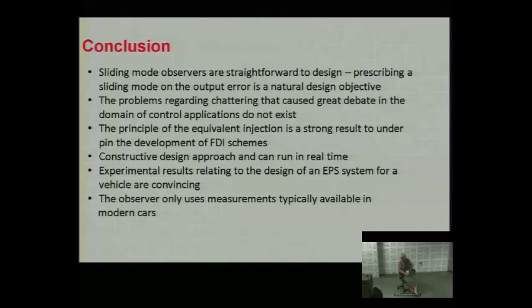The problem with feed-forward control is frequently we don't know the signal. But if you have a reference signal, frequently you would use a feed-forward component of the reference signal within your controller. So we would do exactly the same with the estimate of the disturbance signal that came from the unknown input observer. Does that answer the question?